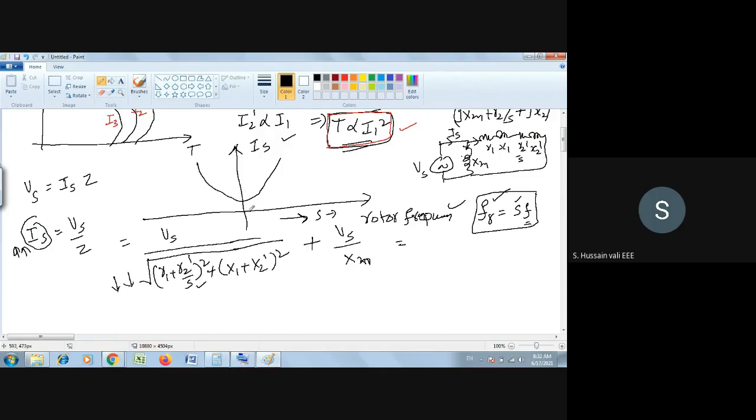See here, once again I will tell you the relationship between rotor frequency and the stator current. We are drawing the graph now. For example, the rotor frequency increases in this direction, that is the x-axis. When you increase the rotor frequency, it means you are increasing the slip. Why is it so? Because by having a constant stator frequency of 50 Hz, you are increasing rotor frequency. It means you are increasing slip. Then only your rotor frequency will increase.